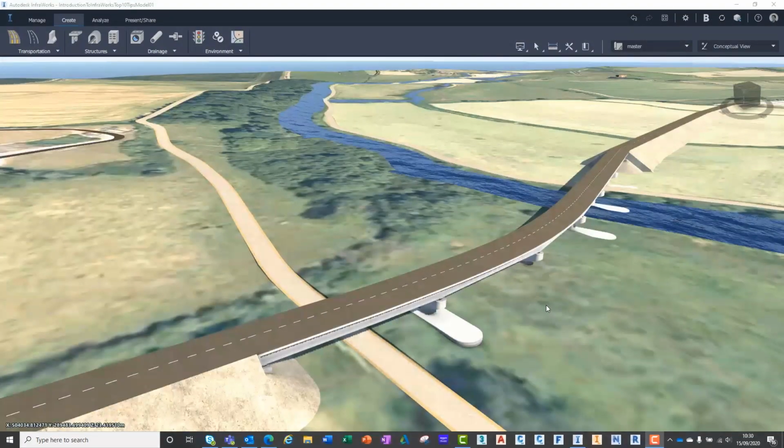As we have created a component road, we can include additional linear elements such as barriers, additional lanes, fencing, curbs, and so on. As we're on the subject, it is worth explaining the two different types of roads InfraWorks has to offer: component roads and planning roads. Component roads, as described, have the versatility to include additional items like the construction of a Civil 3D corridor and would be used for detailed design purposes.